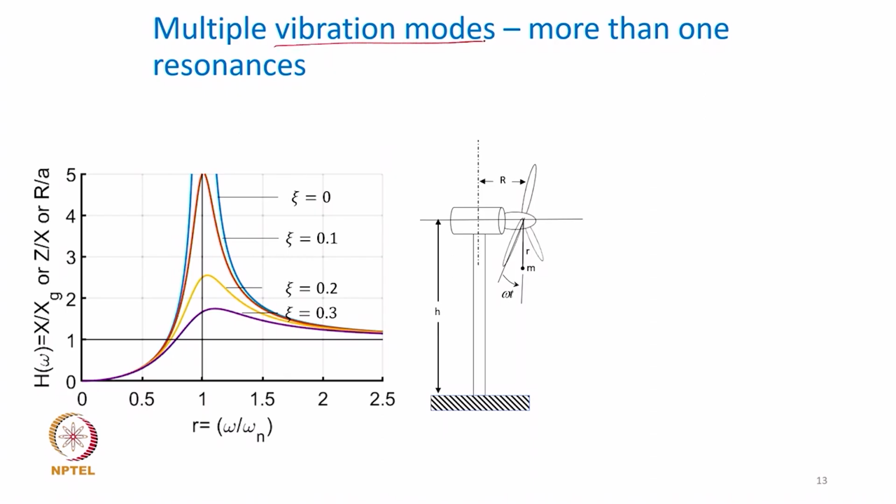For example, again let me come back to this example which we have been discussing many times over right from the beginning, of a windmill, a nacelle sitting on the top of the column, and then we discussed that this unbalance in the rotor blades would generate bending vibration, it would generate torsional excitation to the system, and as one extreme case can also generate the vertical longitudinal vibration, which actually means that the same rotor is going to excite 3 different vibratory modes.